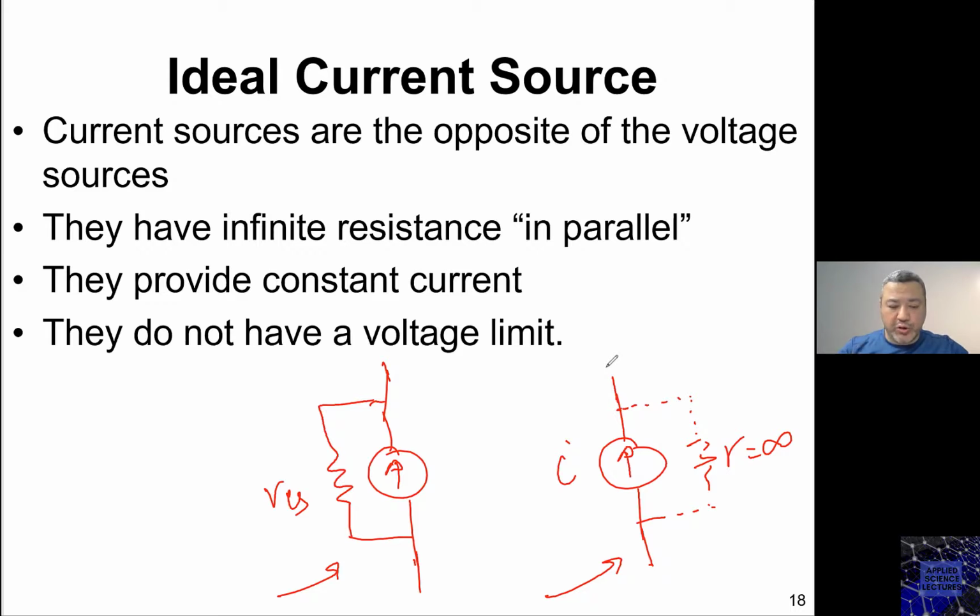If you try to load your power supply, for example your mobile charger, which is a voltage source, with more than the power it can handle, you will either burn the charger, or if it has a protection circuit inside, you will destroy the fuse inside. And this is another feature that adds to the cost of your power supply.